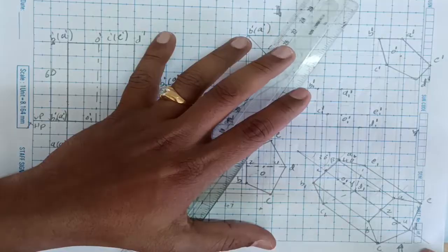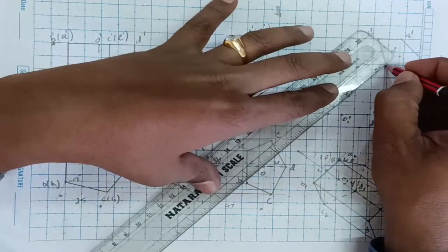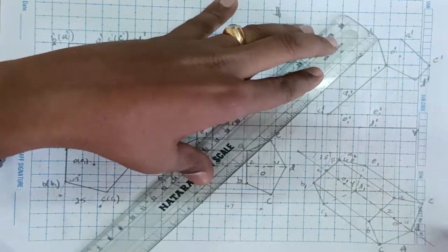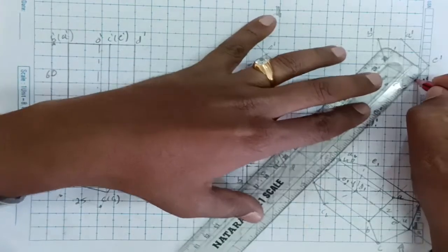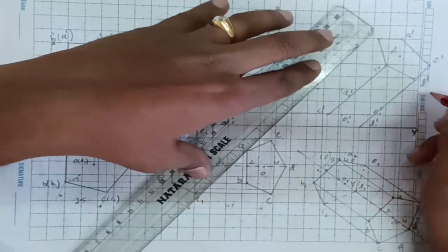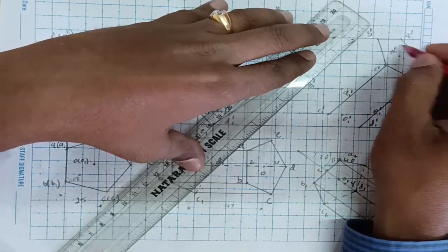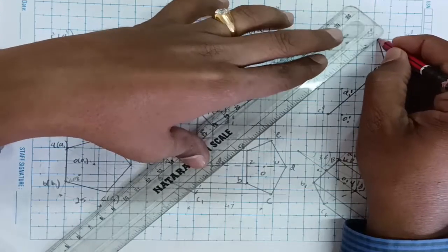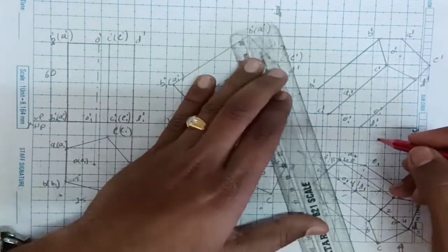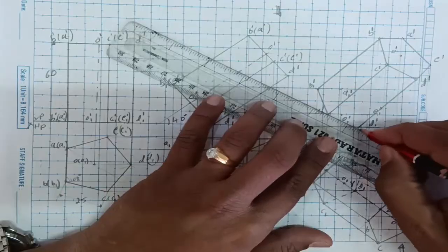And now check which point I am coming first. C and D is coming first, that's why C dash to C1 dash, it will be definitely visible. So join that, C dash to C1 dash, and then D dash to D1 dash also visible, make it visible. And while joining remaining, if it comes inside the frame it is hidden, outside the frame is visible. Now B1 dash, B dash, I am joining, it is coming outside, so it will be visible, and you can join the borders here with the visible.